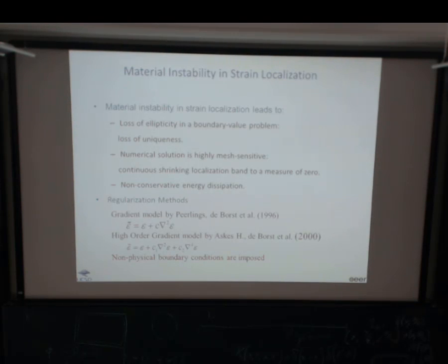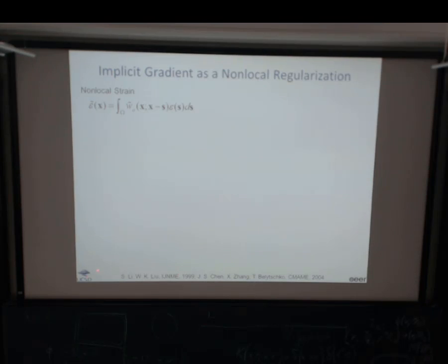So here, I'm extending the work of RKPM, and also in the earlier days, there was work also from Wing-Kam Liu's group on something called synchronized convergence. What they tried to achieve at that time, for a different purpose, was to hopefully construct an approximation space such that, for example, the convergence rate in H1 norm is about the same as the convergence rate in L2 norm.